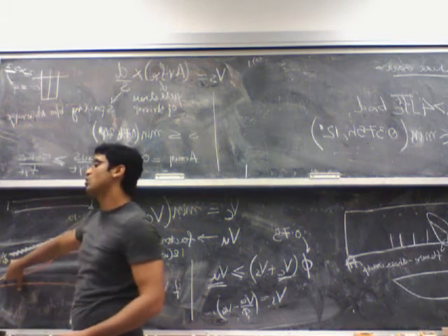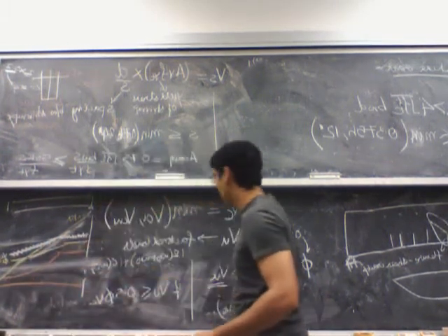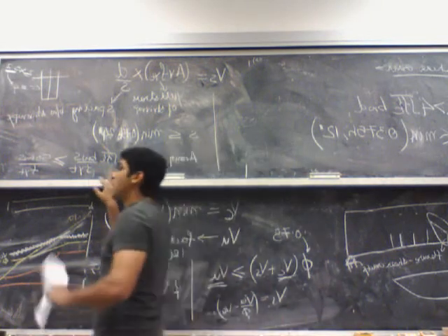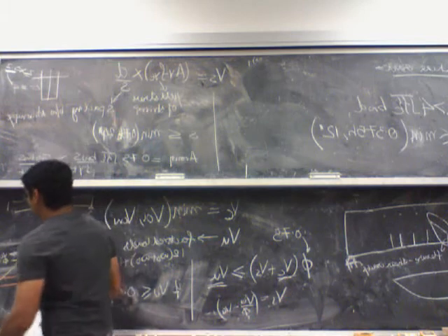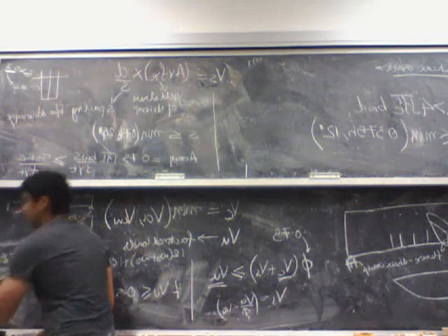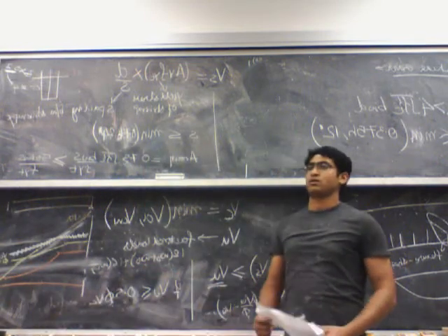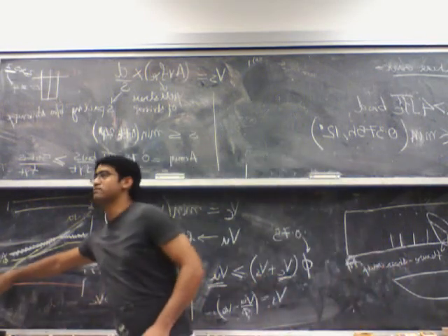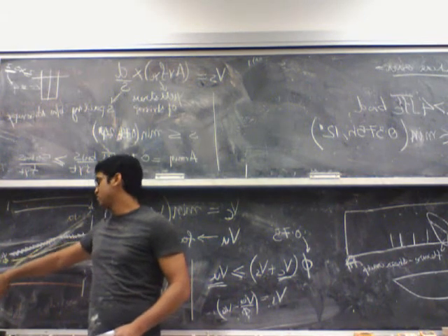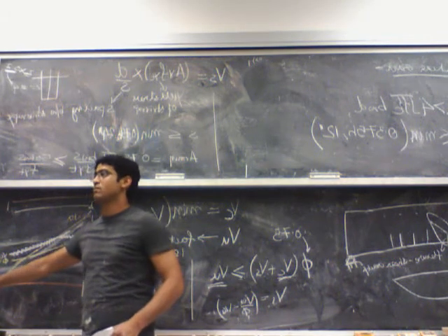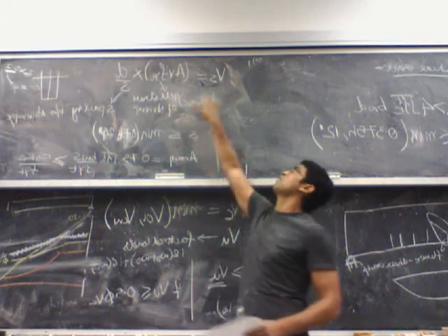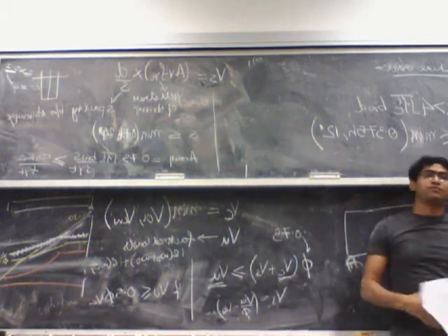Within this range, even though you don't need any stirrups based on this formula, you still go ahead and provide the minimum required. You only don't provide any stirrups if your VU is less than 0.5 times phi times VC. So only beyond this point you can say that, okay, I don't need to provide stirrups, which is 0.5 times phi times VC. Above that, you have to provide some amount of stirrups, which can be either the minimum or based on the formula for VS.